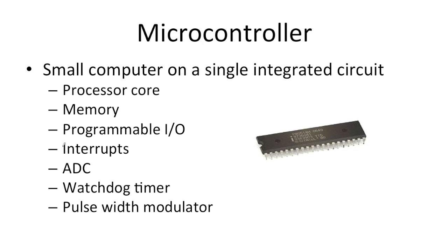Interrupts are a means of providing signals from the outside world to the microcontroller to alert of certain events that are happening. So for instance, if you interfaced a keyboard to your microcontroller, then every time a keystroke is pressed, the interrupt signal is going to tell the microcontroller to leave everything it's doing, attend to the keystroke, and then resume operation once the keystrokes have been handled.